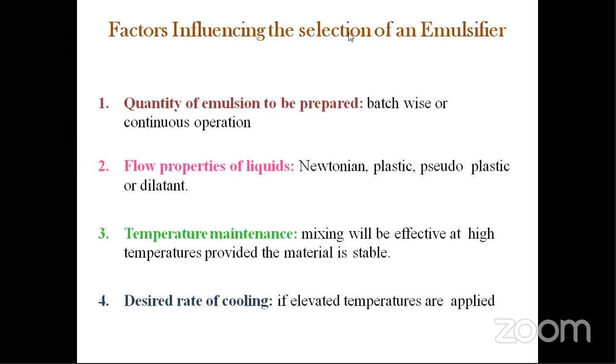During the emulsification process, if your equipment generates some heat, side by side you have to use a cooling jacket or cooling pipe which contains cool water, and which helps the mixture to cool down after the heat is reached. After getting heated, it is automatically cooled down to a certain temperature.